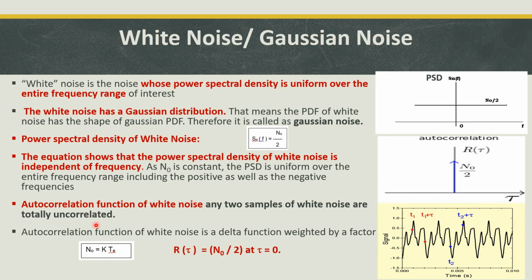Cross correlation means the correlation or similarity between two different signals. Autocorrelation means we identify the correlation between one point of the signal and another point within the single signal itself at a different time slot. The correlation or similarity available is calculated by using autocorrelation.